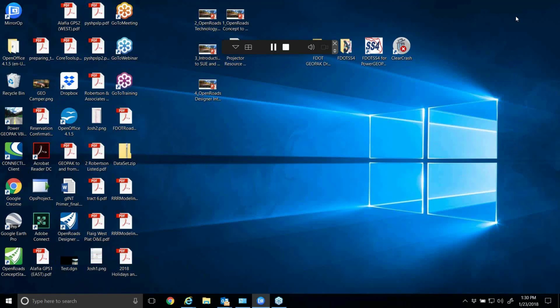we're going to have a network, and you will have multiple networks along most projects with GEOPAK drainage. You're going to have a network. It's going to have a certain amount of inlets, certain amount of junction boxes. They're connected with or through the conveyance system, and they're going to go to one single outfall. Then you're going to move literally a little further down the road. More inlets, more junction boxes, more pipes and conveyance system. That's going to go to another single outfall.